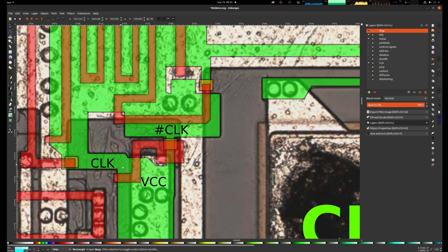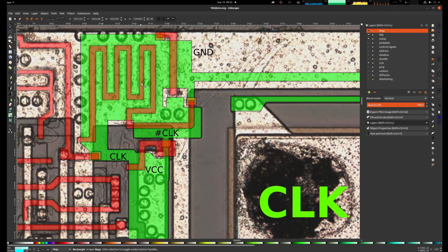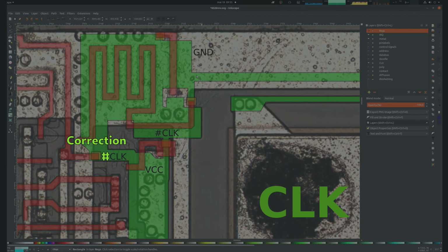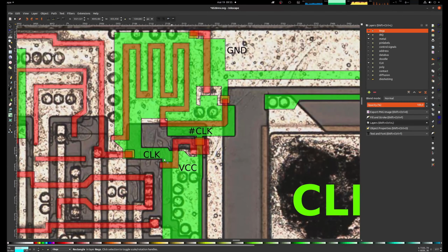So instead of having this large transistor here in a large pull-up or a hard pull-up, it just turns off basically here. So it's an amplification. And you can see this transistor is just much larger, so you get the same signal again as you had to begin with, with a little bit of a propagation delay though, but that's okay. Probably, I hope.